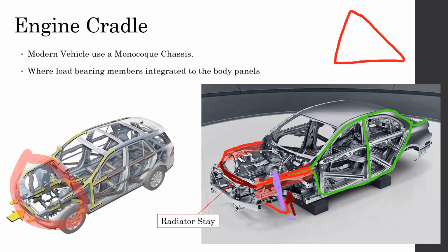When you need even more additional support, you have something called these bars. You can see there are two bars here. These are called strut braces. They provide even more strength, right? Once you put all of these things together, only then do you get the strength. Since you don't have a separate chassis, this body acts as the chassis. This needs triangulation, and once you triangulate everything, it acts like a box.